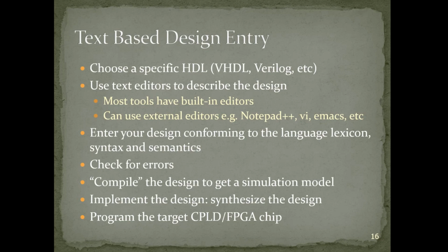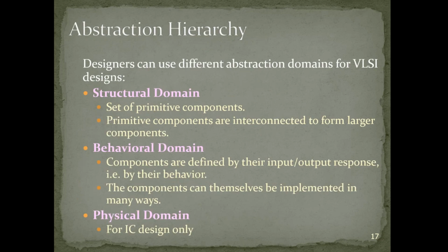And that will create ultimately a programming file that we can just upload into a complex programmable logic device like a CPLD or FPGA, and that will program that chip to perform that particular digital functionality. So there you go. That's kind of the typical workflow that we tend to employ in connection to the various forms of entry for this type of hardware description language.